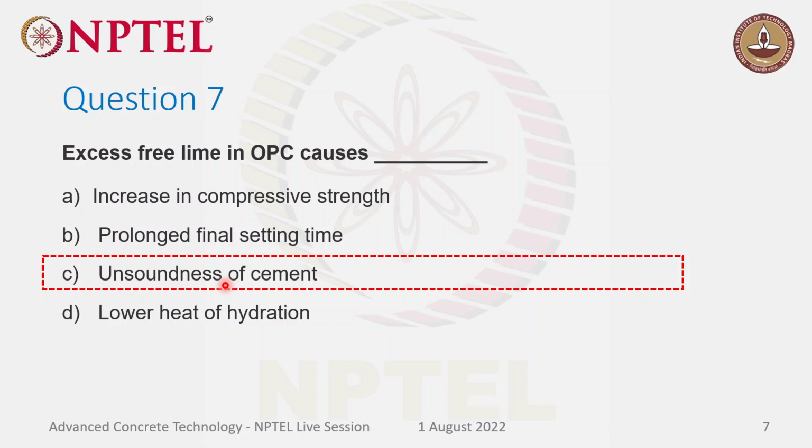You can check the quality of the water used for curing. I found the quality of the water, the chloride is around 550. Oh, okay, so it can be an issue. Sir, actually, I could not exactly remember what the limit for chlorides is for this curing water.